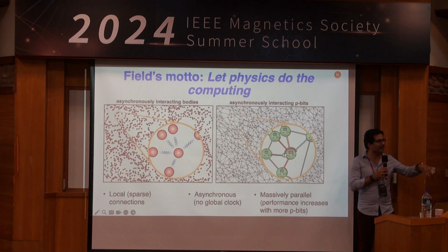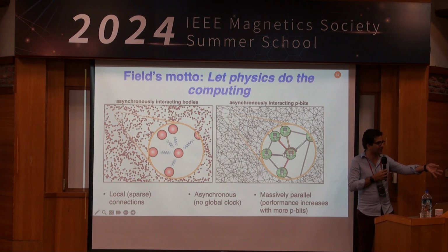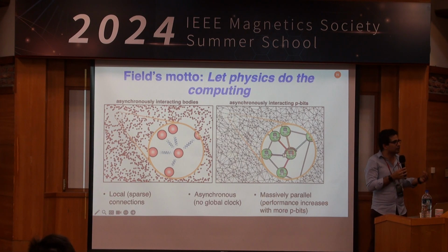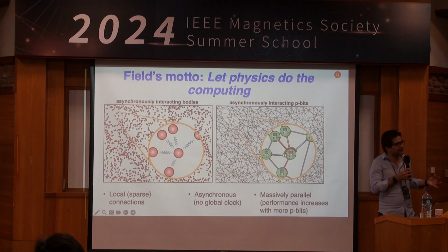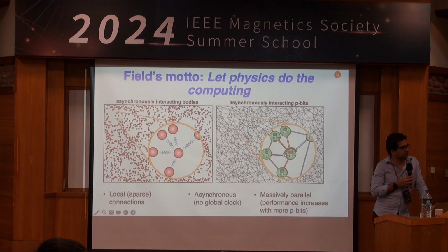So the entire MTJ thinking is changed, and there are ways of making it very hard against write currents, which is exactly the opposite of what you want in an STT-MRAM situation. But you want it to be magnetically soft. Remarkably, because of the nonlinear nature of magnetism, in-plane magnets, especially with double free layers and so on, are very hard to write, but they're magnetically very soft. These are real experiments. But the critical thing is the read disturb, right? So the read current will maybe become the write current for this.